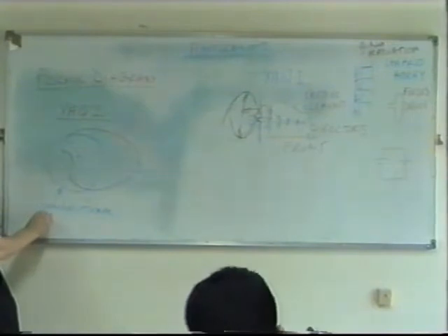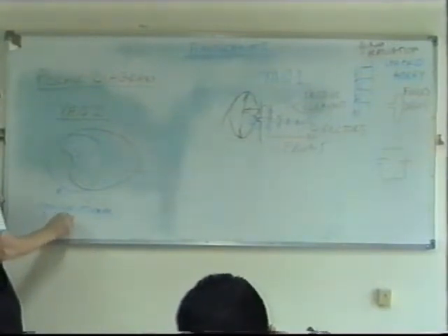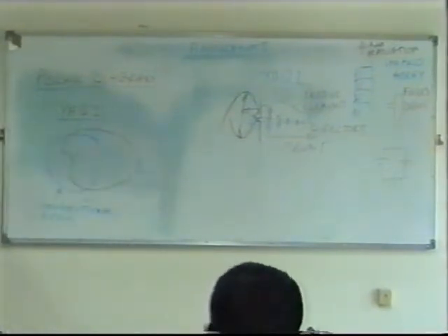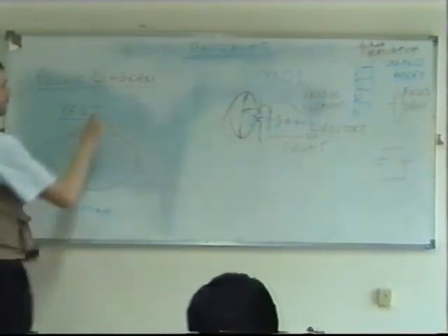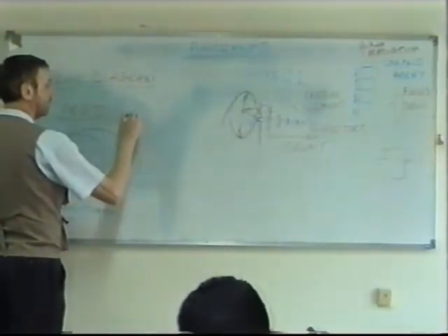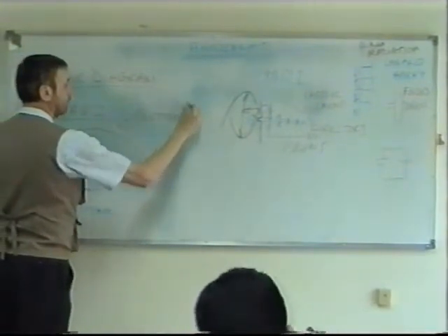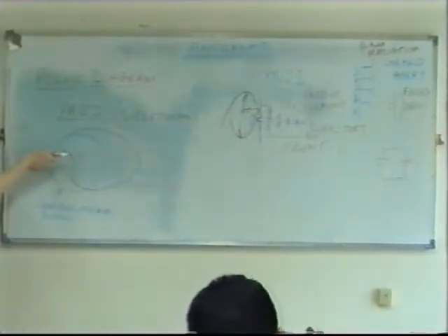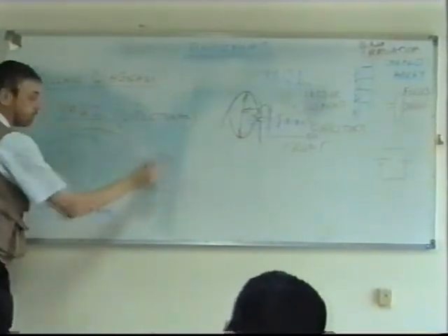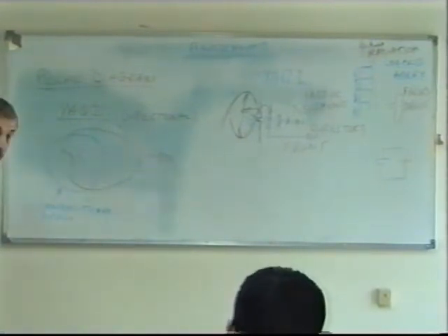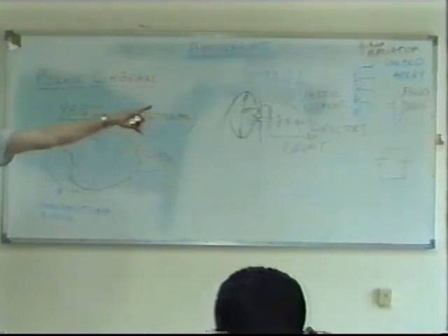This is the omnidirectional dipole, but here the Yagi we can see is directional, isn't it? It's an example of a directional antenna. And in our case, the direction is this direction. And it has a lot of advantages. Yes, it's a top view, exactly, looking down on top of the antenna.